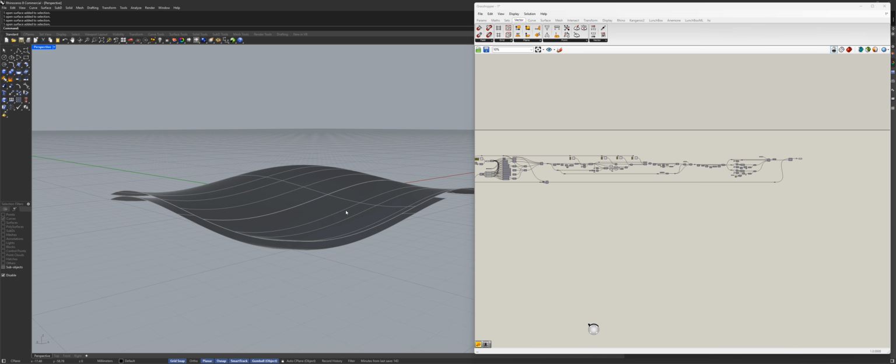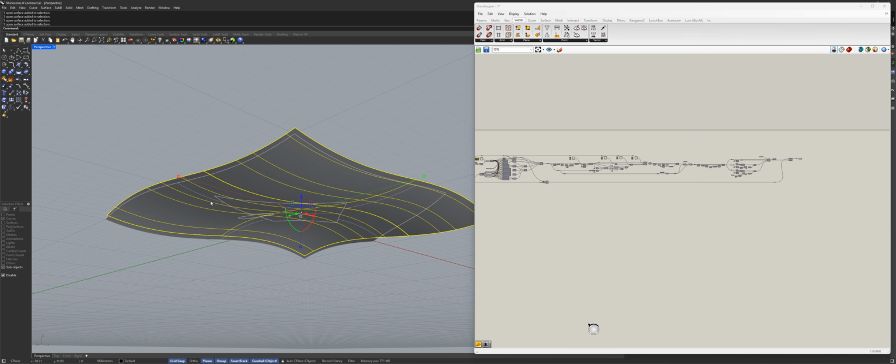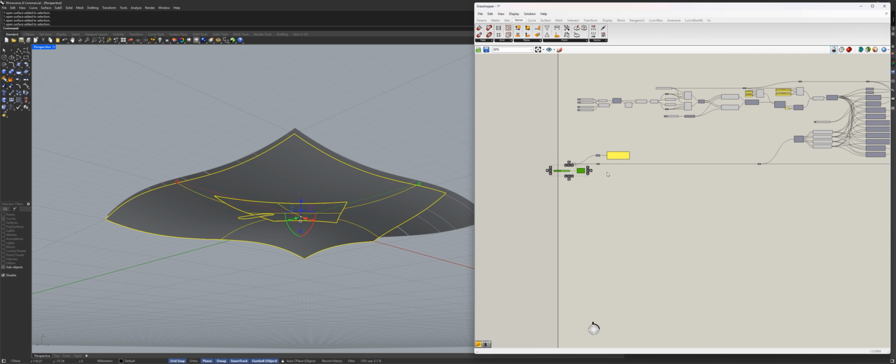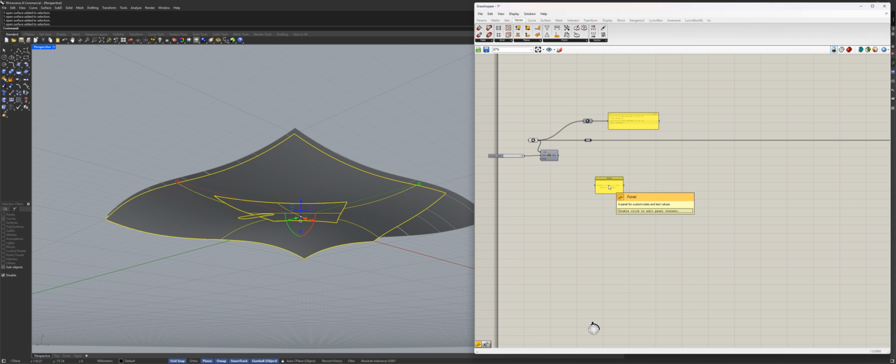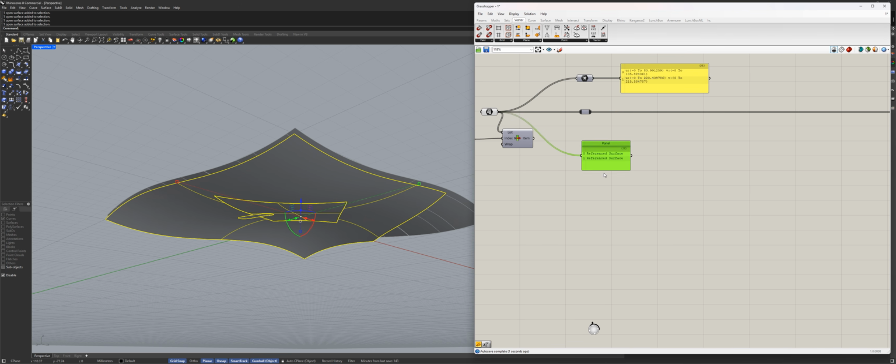All right. So I will create a pattern on this surface, and then we will project it on our collection of surfaces. But as I said, the collection of surfaces right now is just a list of individual surfaces, right? So if I look at our imported geometry, you're going to see there are two separate surfaces, right? And this is a big problem because when I project, it will project on them individually. I wanted it to project on them as a whole, as if these two surfaces become one general geometric block. And for that, we use the concept of polysurfaces or BREPs.